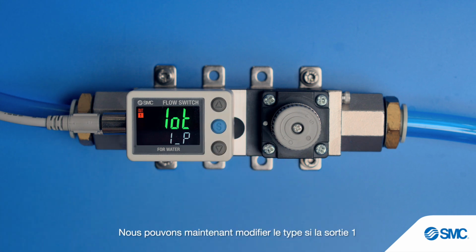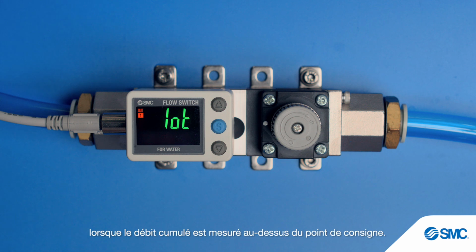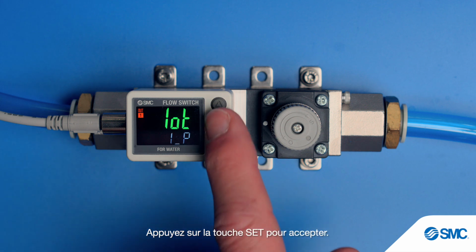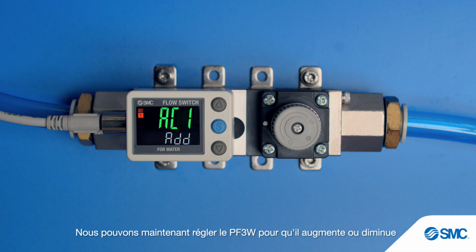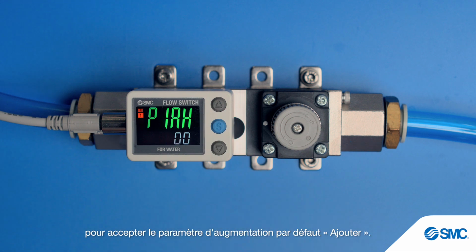Now we can change the type, if output 1 is on either below or above the threshold. Here we'll leave the setting as 1_p, meaning the output is on when the accumulated flow is measured above the set point. Press the set button to accept. Now we can set the PF3W to increase or decrease the accumulated flow as fluid passes through the device by pressing the up or down buttons. Again, we'll press the set button to accept the default add increase setting.